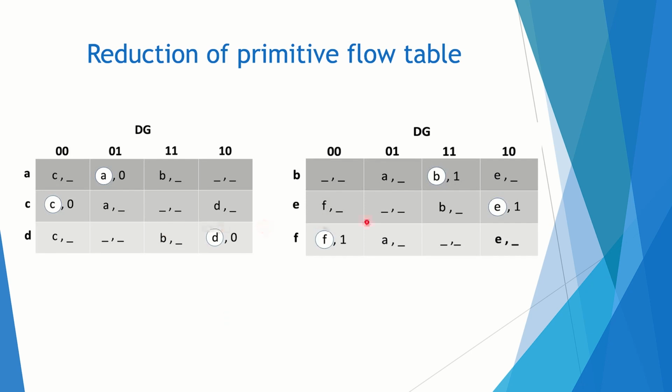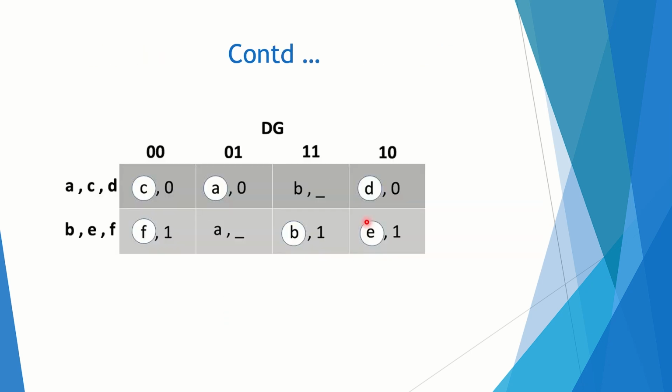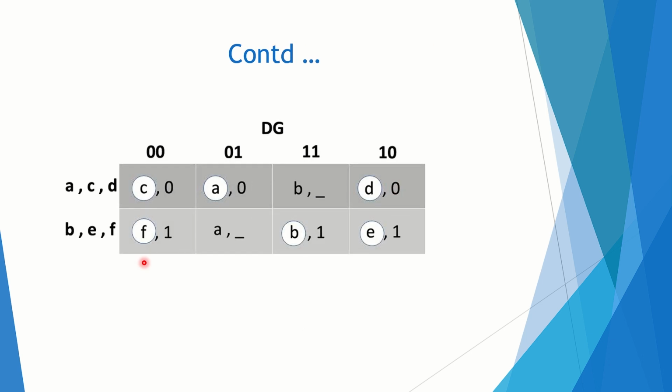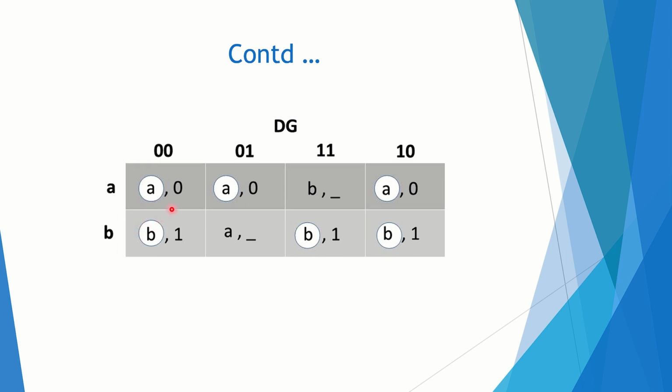So yeah, split the table and then combined into two. So ACD combined into two. See here. So you can see here the ACD, this I have merged into one. So again merged into one and then combined. So that is, so we can have this. We can have just two states because they are all equivalent. It's a new modified table.